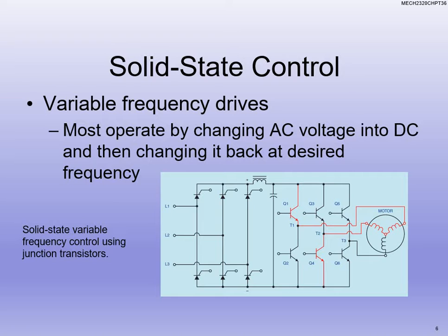All right, we're choking it so that we can control it. We put a capacitor across it. We're really filtering it so that we fine tune that DC, because remember, DC is either genuinely on or off, right? So we have to fine tune it. If we're using 24 volts, we really want to flatten that out so that it's 24 volts.